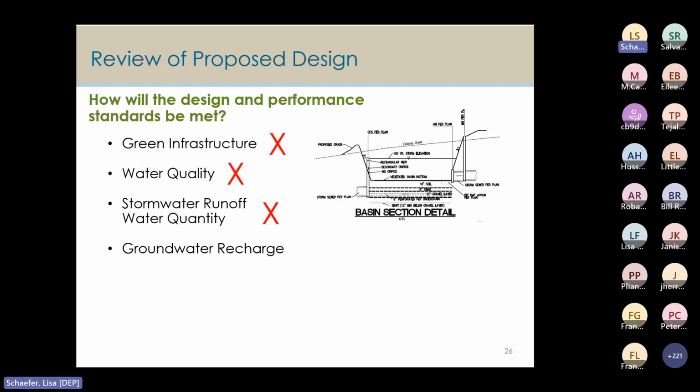Now for groundwater recharge, this is where it gets very interesting. Okay, for groundwater recharge, the report states the project demonstrates compliance with subsection 5.4 of the rules because all of the runoff is infiltrated. No, that's another error. They're only proposing under-drain BMPs.